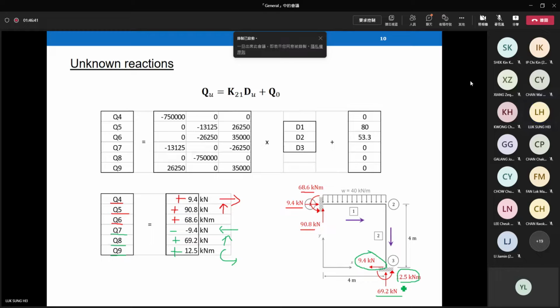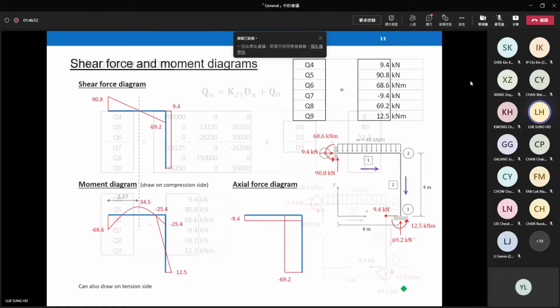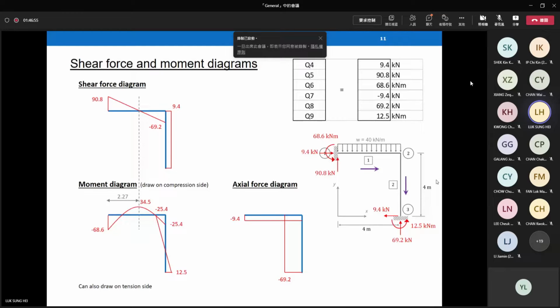Becomes something like a force diagram. From the force diagram, you believe that you can draw the shear and moment diagrams immediately. From the force diagrams, you can draw these kind of pictures. Actual force diagram easy, right? Because you can see the actual force directly from the picture. Element 1 under compression 9.5, element 2 under compression 69.2. I take compression as negative, so you can see that the actual force diagram involves only negative values.